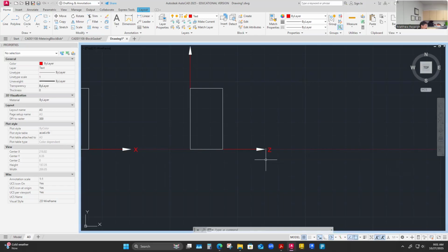And then generally we only use 2 sizes. We use small ones for dimensions, which have an ASME standard. 0.125 is the length in inches, and 3 is the length in millimeters. That's why our normal text height in inches is 0.125, and our normal arrow length is 0.125, and then the width is a third of that, which is 0.04. I mean, that's hard, but you start to memorize this stuff and then you use it.